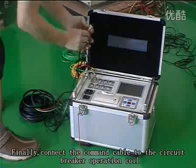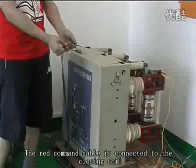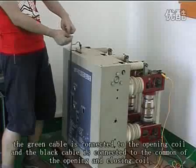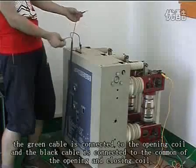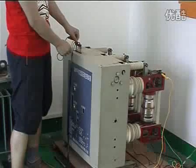Finally, connect the command cable to the circuit breaker operation coil. The red command cable is connected to the closing coil. The green cable is connected to the opening coil, and the black cable is connected to the common of the opening and closing coil.